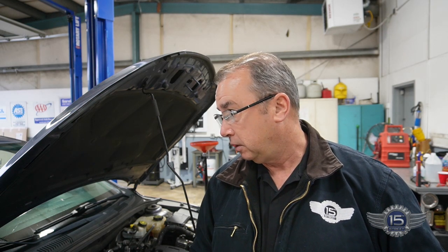So that purge valve is pretty cheap, super easy to change. I'm not going to mess around anymore. I just ordered a purge valve. I'm going to put it on and see if our conditions improve. If they do not improve, then we'll continue on. But I suspect we have a bad purge valve that is over purging. If that's not the case, then our problem has to be in the canister, because if we isolate the purge system from the intake manifold, our problems go away. So the purge valve is on its way. I'm going to install it and I'll bring it back in.